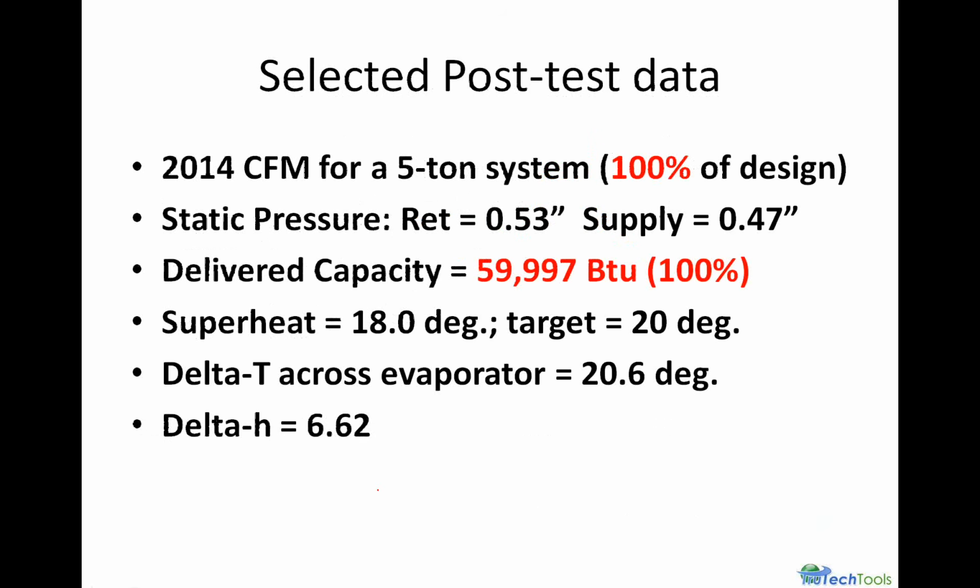When we looked at the post, we got the airflow up to 2014 CFM, 100% of its rated design. Return static was 0.53, supply 0.47. Still high on the supply and return air static.